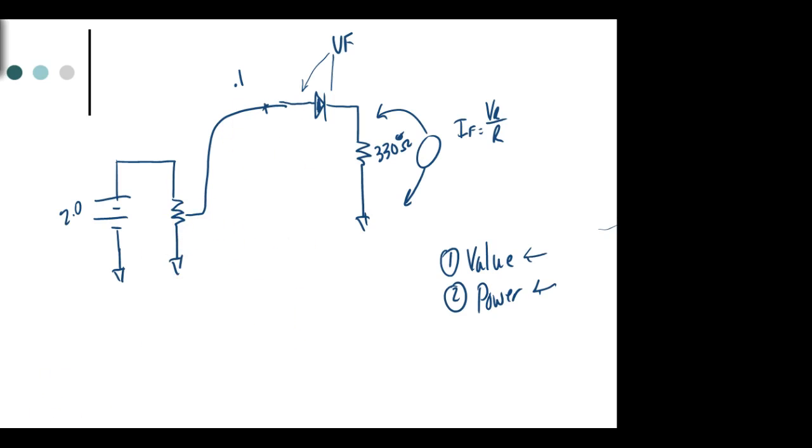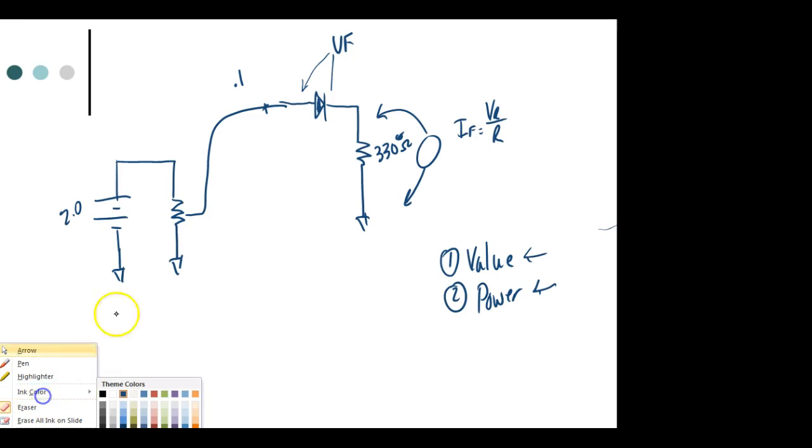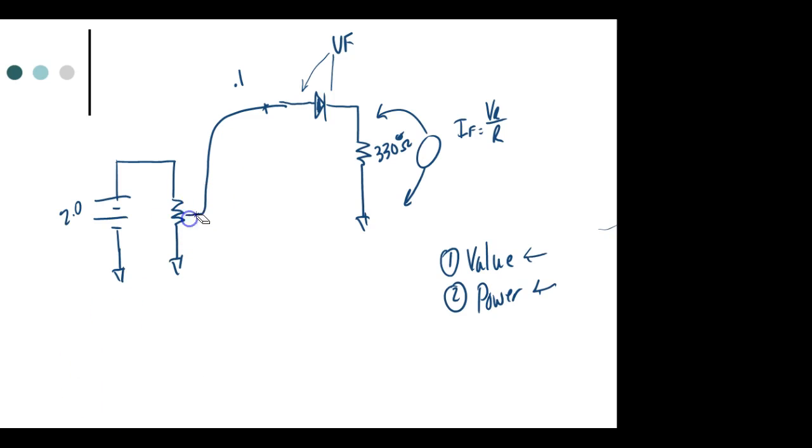If I adjust my pot down to the bottom, what would it measure? 0. If I adjust it all the way up, it measures what we're going to get. We're probably going to have to put in more than 2 volts to get 750 millivolts out. It doesn't make any difference.